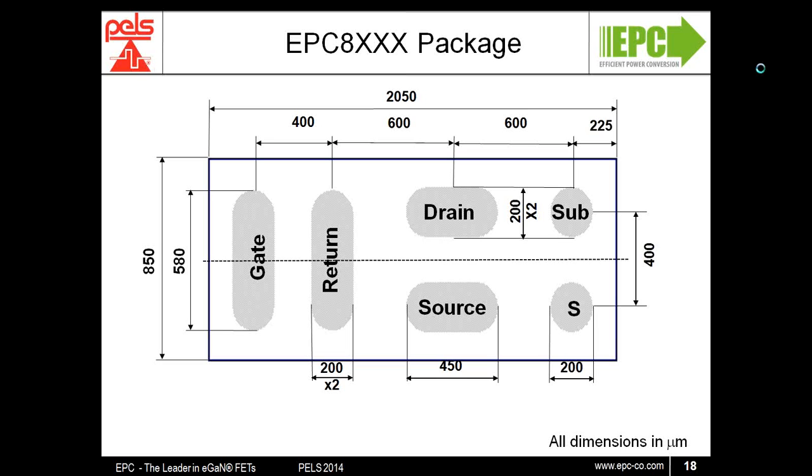We can see that for a half-bridge, the bus supply comes in at the drain of the top device, goes through the device to the source, down to the drain of the second device, and down to the source, and then to ground. We can see this power path current is orthogonal to the gate drive currents, which come in from the left into the gate and return through a separate gate return path to minimize common source inductance. As stated, these are orthogonal to each other.